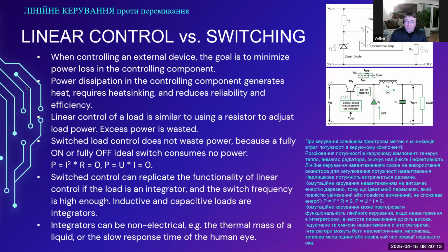And most loads that we're dealing with will be integrators. For example, if you're switching an electric motor with several kilohertz of frequency, the inductance of the electric motor and the mechanical slowness of the rotation of the motor will effectively integrate the high frequency power switching.